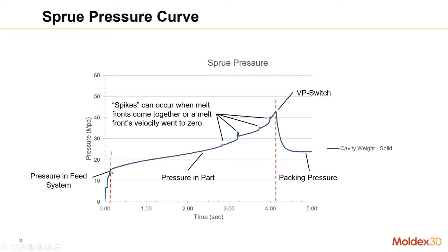During the filling stage, or the injection stage, we're using velocity to push the material through our empty volume. Once we've filled that volume, we're going to use pressure to continually introduce material into the part volume, or ultimately into the runner volume as well.